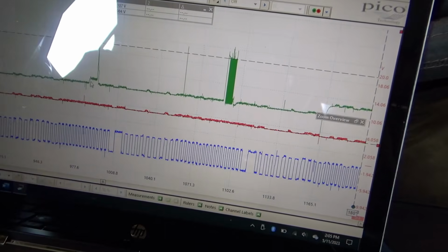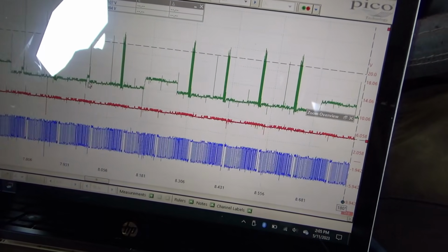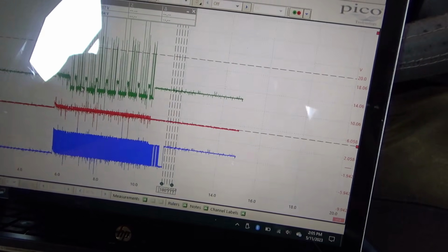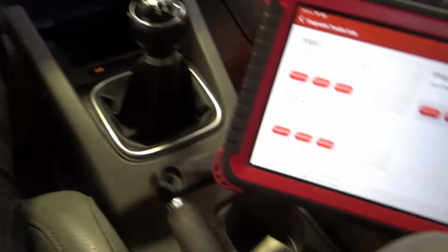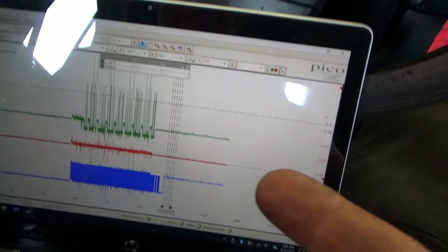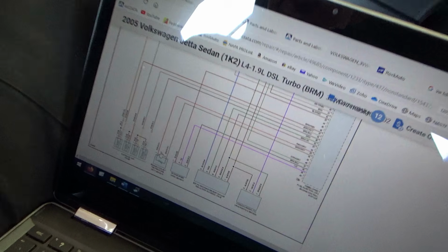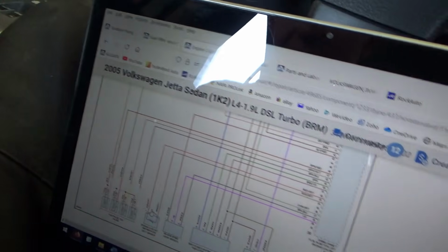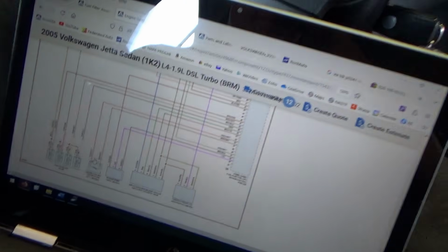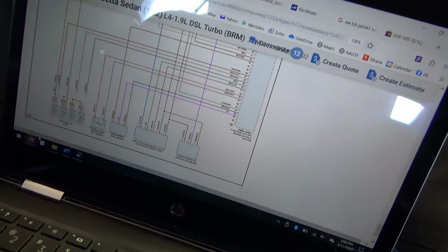We could probe the feed wire to see if the injector is actually opening. Let's do that, and then we'll chase the 341 code. There's nothing on Google to help us this time. Alright, so I added channel 4 to the common brown and yellow wire. I assume that's the power feed, or the high side driver for the injectors. So now in the scope,